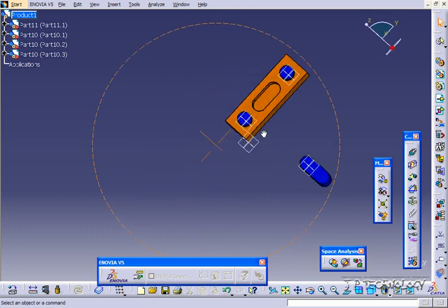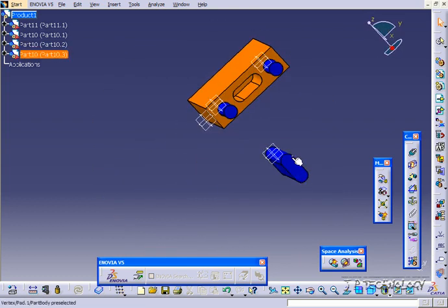Now with a part such as this is where we're going to run into problems with using the snap feature. When we used the coincident mate before, we were able to make a coincident mate between this axis here and this axis here. When we make the other coincident mate, you have like a pivoting point, and this will whip around and you'll have it slotted in. Now I'm going to try to do the same thing using the snap feature, but you're going to see that we don't get the result we want.